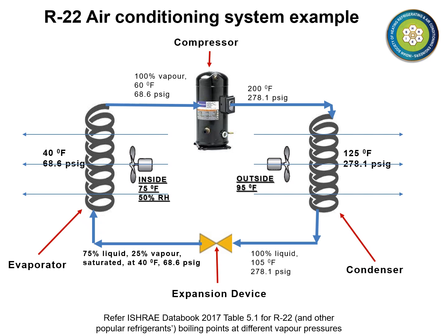By the time it finishes its journey through the condenser, it has fully changed phase to liquid. And when it reaches the expansion device inlet, it is a 100% subcooled liquid at about 105 degrees Fahrenheit. We hope you now have a clear idea of how the vapor compression cycle enables absorbing heat from the air conditioned space and rejecting the same into the outside air.